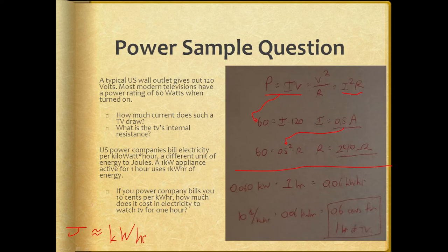And I can prove this by, if you look at the unit of a kilowatt hour, it's literally watts times hours. Watts equals joules per time, so multiplying watts by time just gives you a unit of energy. So, kilowatt hours is a unit of energy. Your house gets billed a number of cents per unit of energy that you use. And the trick to calculating how many kilowatt hours specifically that your house uses is, the definition of a kilowatt hour is literally 1 kilowatt times 1 hour.